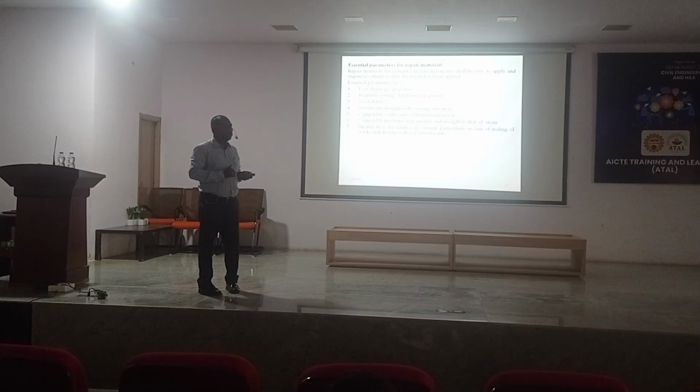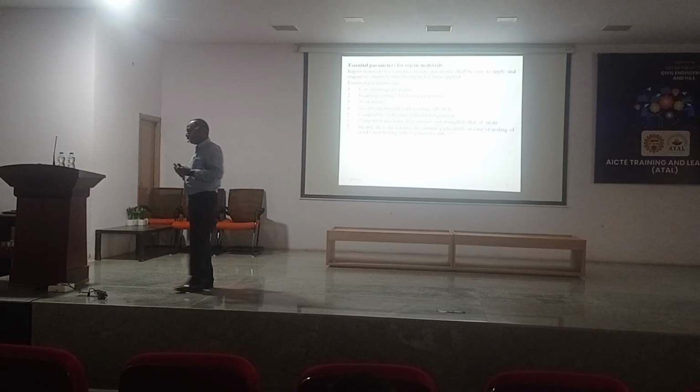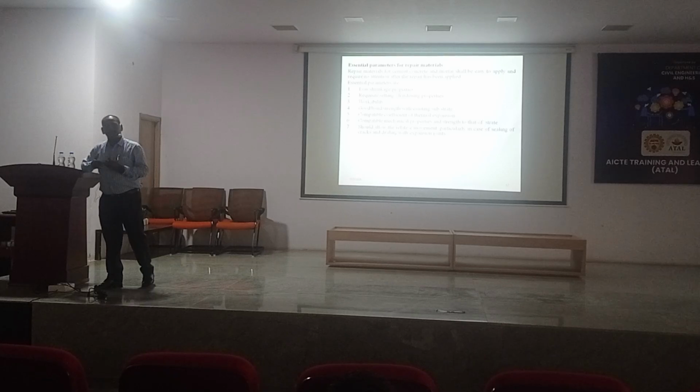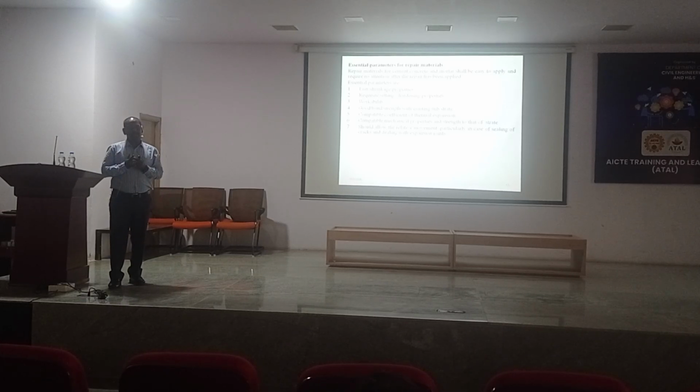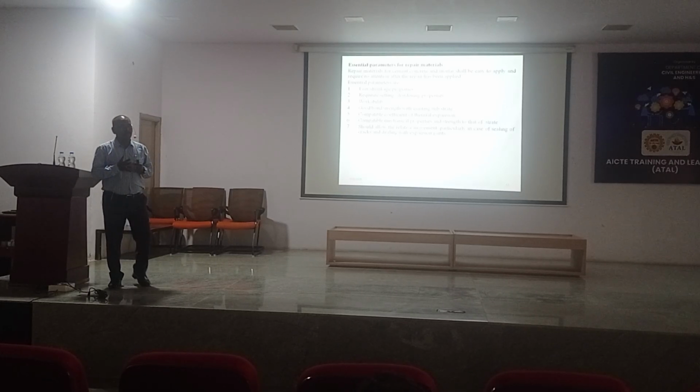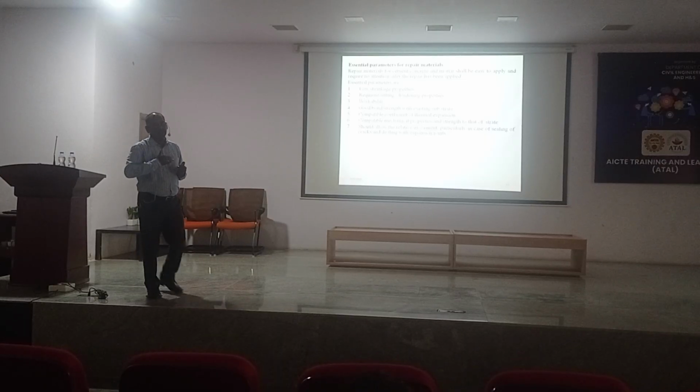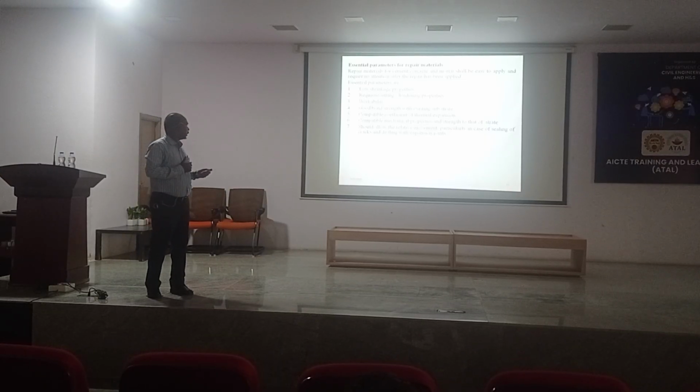And allow the relative movement. Sometimes in bridge repairs, that movement is also there. The new repair should not obstruct the movement of the bridge deck. Okay? Particularly in the sealing of cracks and dealing with external joints.